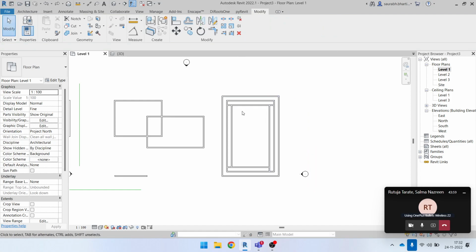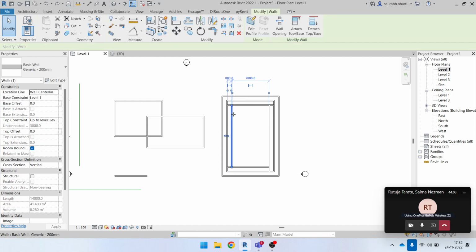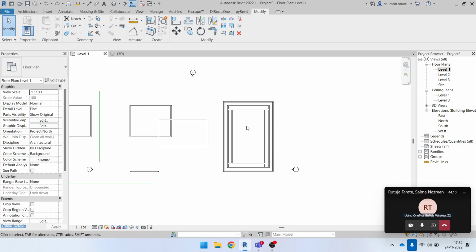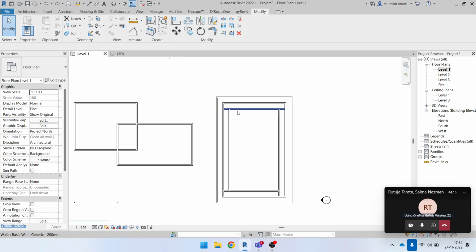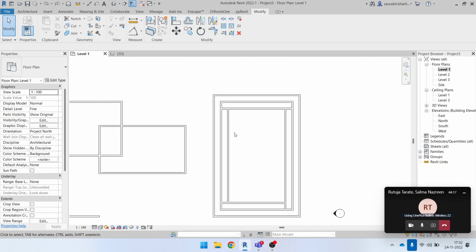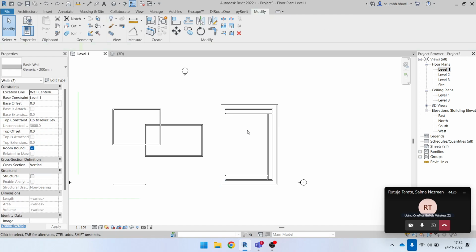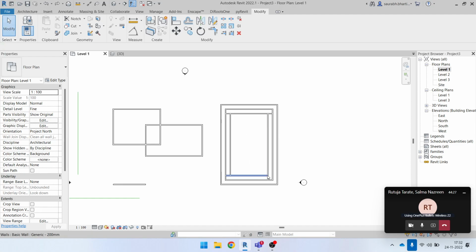Okay. And in AutoCAD also, the delete button works the same as in this one. I'm just selecting this and pressing my delete button, and it is getting deleted here. E is there for the erase option in AutoCAD. And here you can directly use the delete button to delete it. So I can just delete it directly here.